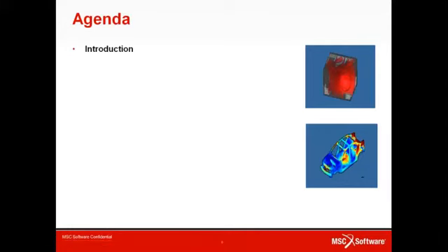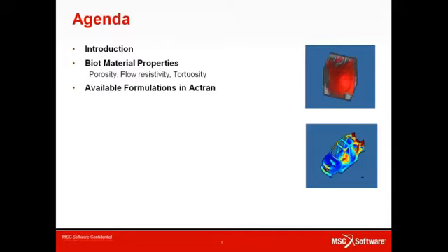First, I will briefly introduce the poro-elastic formulation that is based on the theory developed by Mr. Biot. This theory is based on the knowledge of several mechanical properties that are the so-called Biot properties. I will quickly review the major ones as well as the way these properties can be measured. I will then review the poro-elastic formulations that are available in Actran and compare them qualitatively with each other in terms of accuracy and performance.